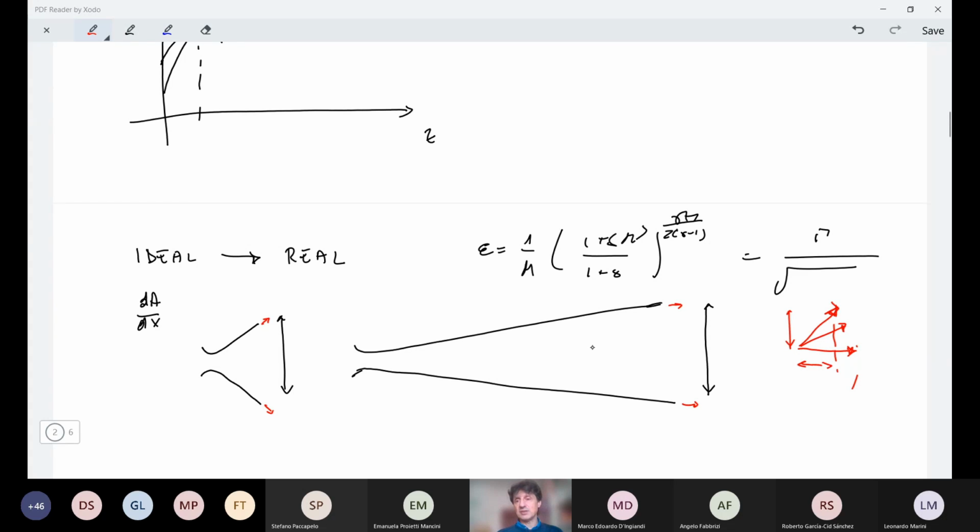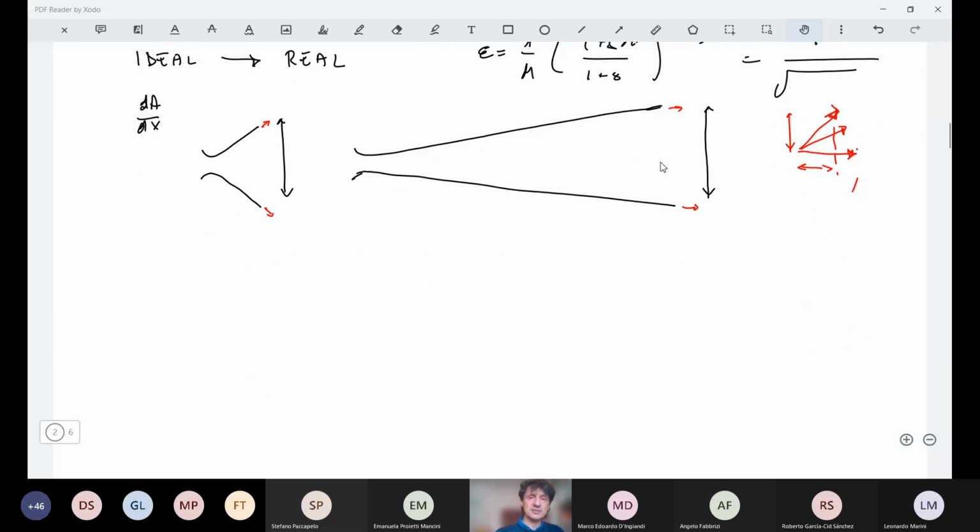So reducing the velocity in the axial direction, and thus the momentum in the axial direction, tells us about the reduction of the thrust due to this shape, due to the fact that we have a higher component in the radial direction. So we have to consider in general what are referred to as divergence losses.